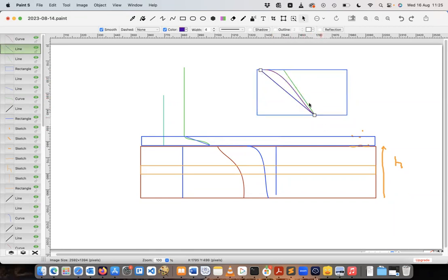We can just solve for steady state, and that will be our concentration profile. Or another way to look at it is the moment I move the surface concentration, the whole profile shifts almost immediately. So if that's the case, this whole profile is moving as I'm shifting what's happening on the surface.